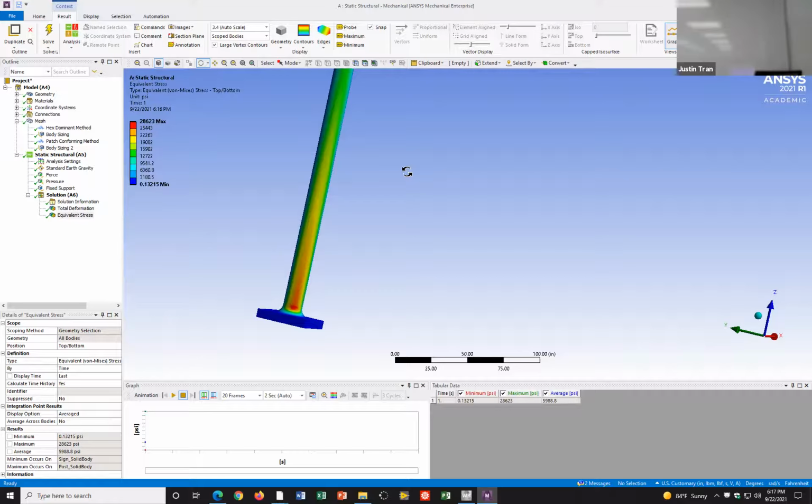It's like 20 feet. Point four. Why does it look so different? It looks like a 0.4 element size with extremely tiny elements. You put 20.4 inches. You see, the total size of this is 20 feet. Oh, so that's the flag. This is the feature size, and that's something we'll go over in the advanced session. So this is looking for any features that are smaller than 0.4 inches and automatically hiding them.